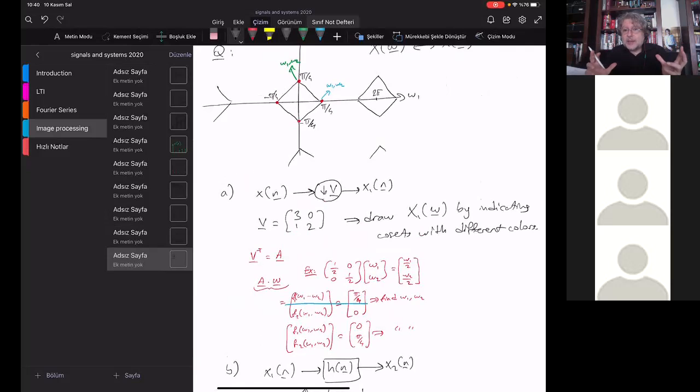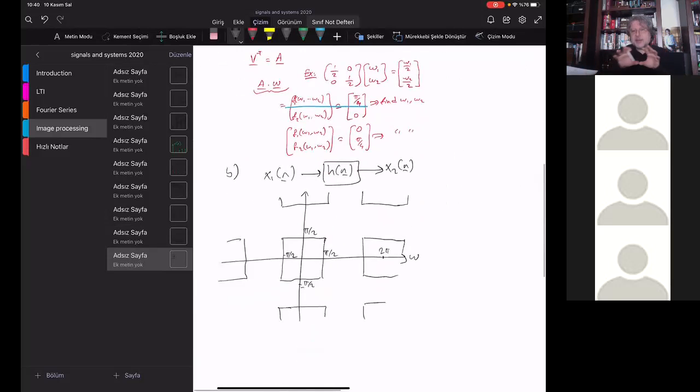And because of it becoming wider, actually, it may be wider than this pi over 2 range. And this low-pass filter will retain only the portion inside it, and all the tail portions that go beyond this rectangular shape low-pass filter support will be cut off. It will be cut off from the center 0, 0. It will be cut off from the replica at 2 pi horizontally, 2 pi vertically, and 2 pi by 2 pi diagonally. All the replicas will be clipped off. If there are some ears, for example, that protrude or extend beyond this rectangular box, those ears will be chopped off. Okay, that's what the Fourier transform of x2 of n will look like.